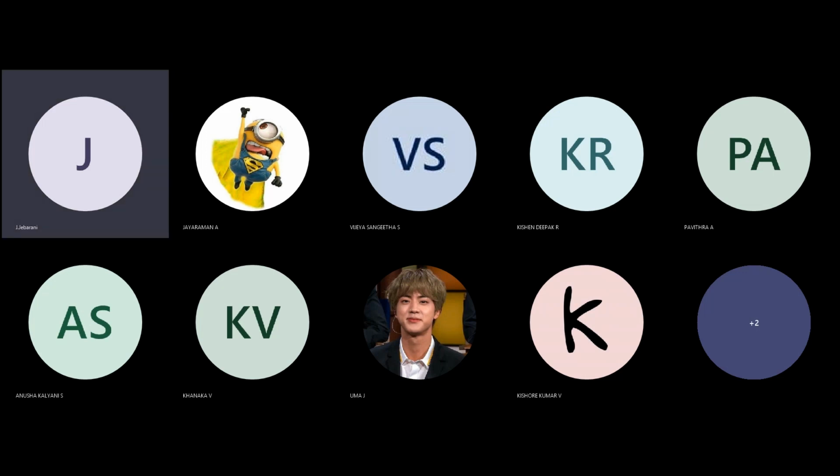So because of its higher viscosity when compared with gas, the water pushes the material to the end of the cavity for final packing. Then valves are closed off, the melt from the injection unit and the water from the pin. A release valve for the water opens, allowing the water to drain from the part. A valve mounted near the end of fill can facilitate the water evacuation using compressed air.